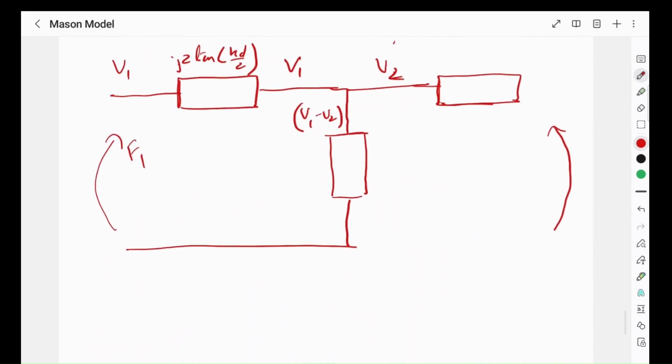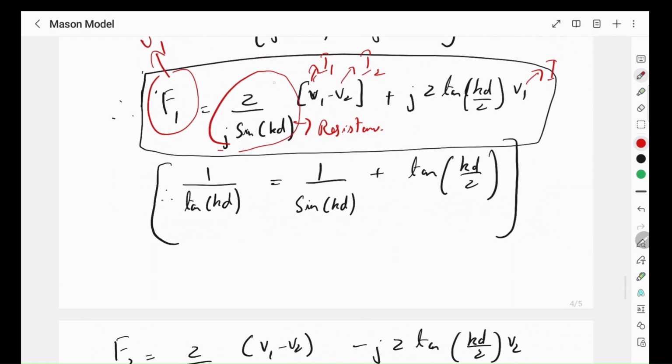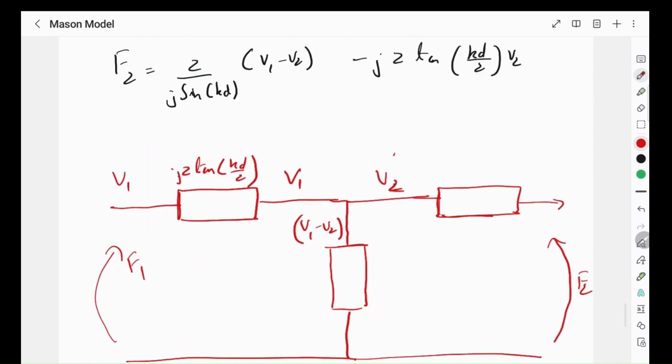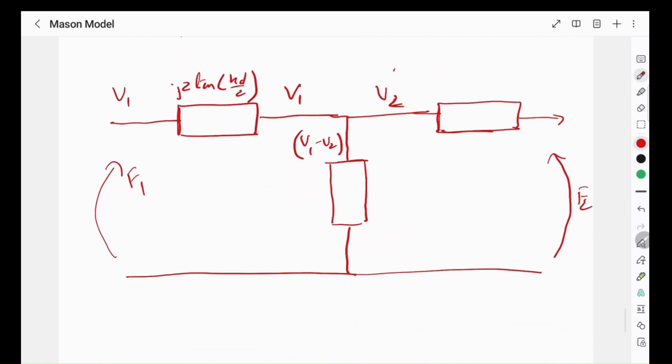So the forces from both sides come here, this F2 force. Similar to the voltage analogy, ultimately your voltage drop, or your force F, is equal to V1 minus V2 into the acoustic impedance term, the resistance, you can call this resistance or acoustic impedance term, into some sine functions. Similarly, you have the current or the velocity here into that resistance. Similarly, on the F2 side, you write it like that in terms of these two and P2.